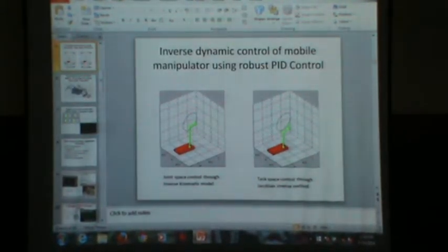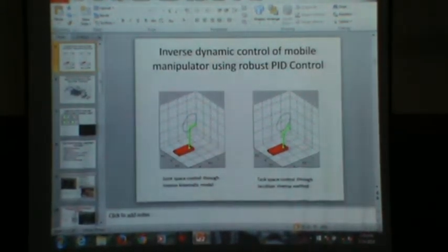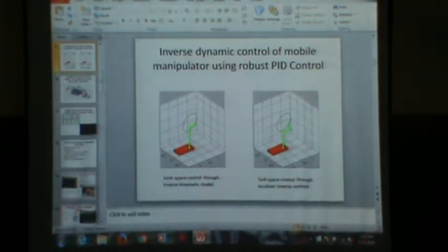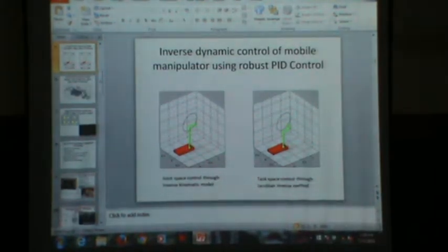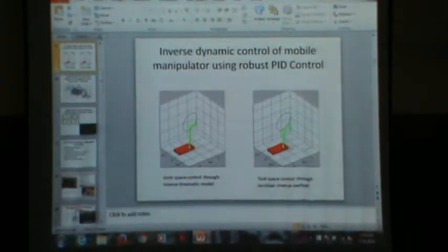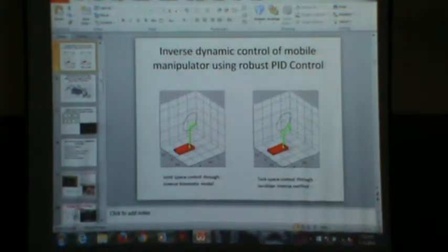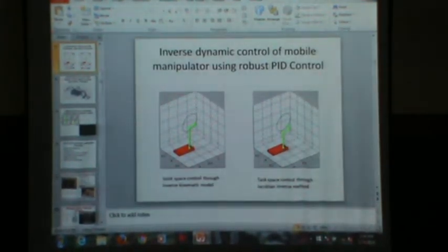So you have a kinematic control, and based on the kinematic control you will make a virtual desired velocity. You will compare that with your velocity and apply the torque or force. This is what we call dynamic control. This is what we call kinematic control. Simply, people call this the inner loop, and this the outer loop.